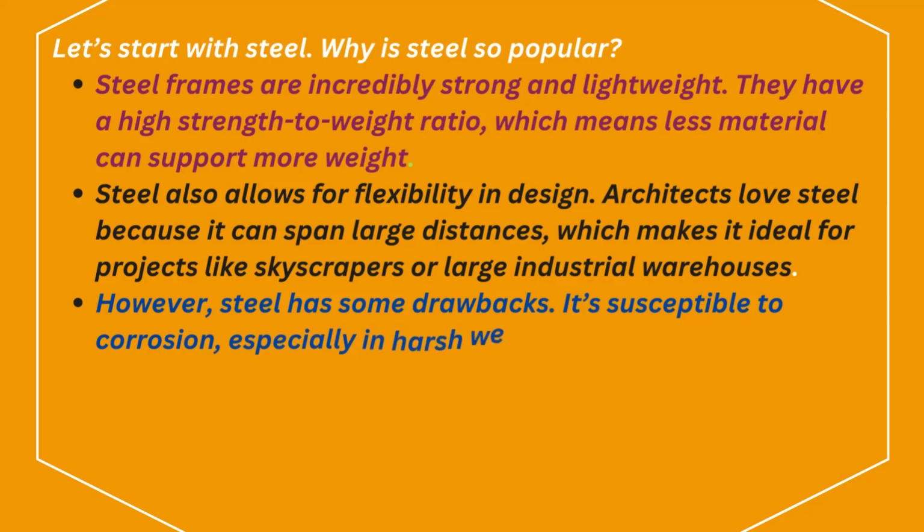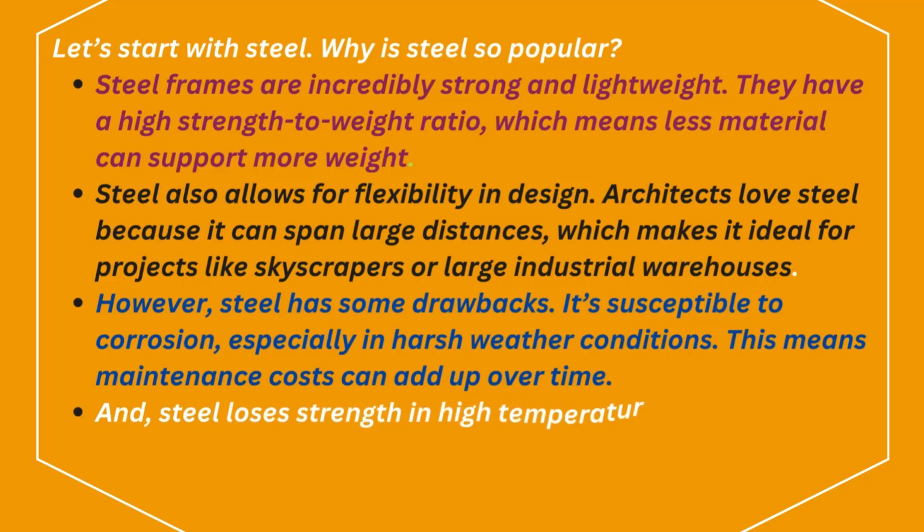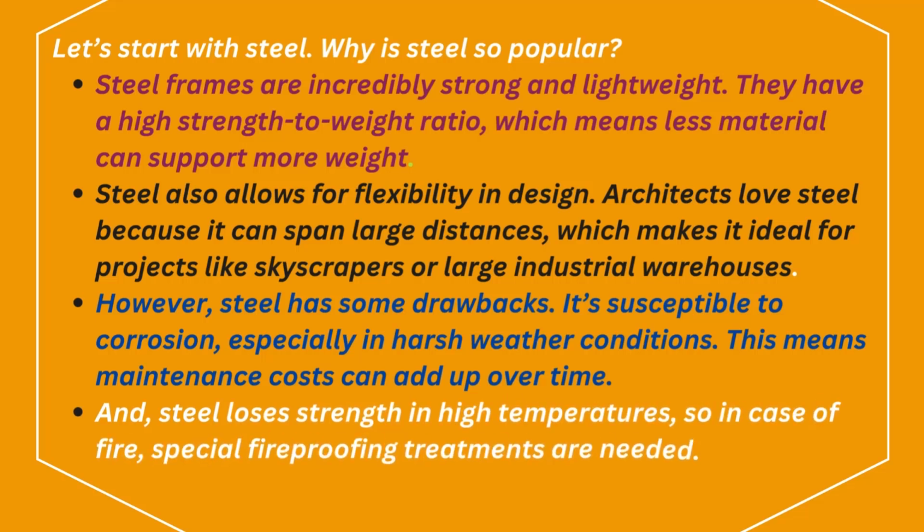However, steel has some drawbacks. It's susceptible to corrosion, especially in harsh weather conditions. This means maintenance costs can add up over time. And steel loses strength in high temperatures, so in case of fire, special fireproofing treatments are needed.